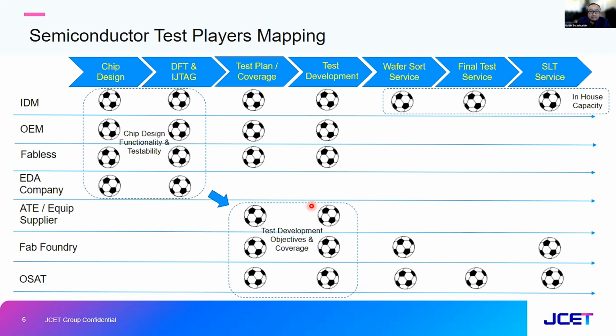parameter tests, AC parametric tests, functional tests, where all these functional tests are normally going to dominate the test time, or the portion of the test program itself. So with that kind of guideline for the OSAT to help you or collaborate in developing the solution for 3D testing, then you will achieve the goal of doing these 3D tests at the OSAT level.